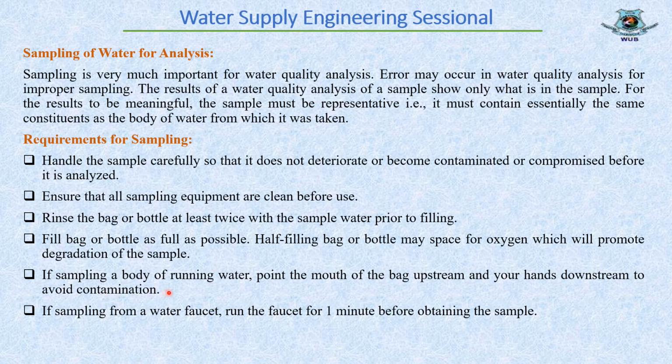If sampling a body of running water, point the mouth of the bag upstream and your hand downstream to avoid contamination. If sampling from a water faucet, that means from a tube or funnel, run the faucet for 1 minute before obtaining the sample so that the faucet becomes clean.